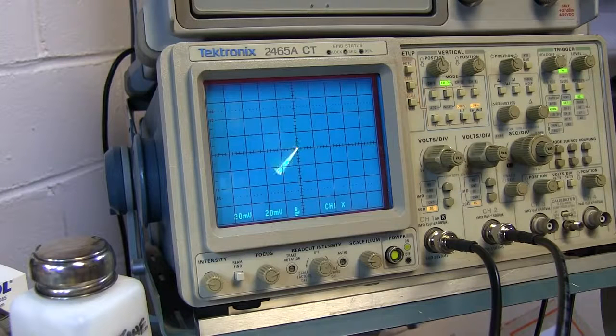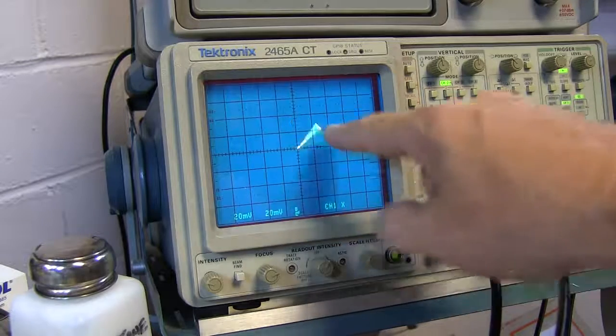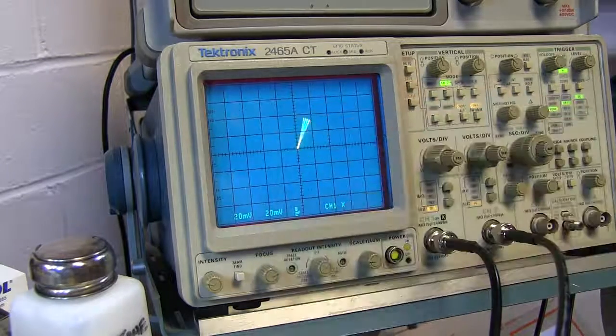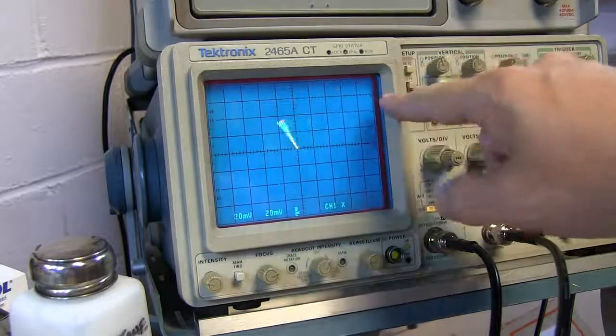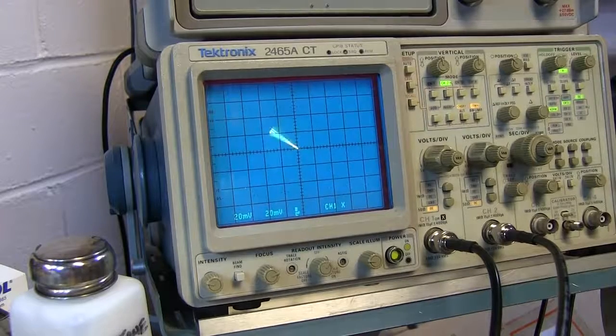If I make that a 2 hertz difference, we'll rotate twice a second, 3 times a second, 4 times a second, and so on. So essentially a frequency offset is represented by spinning that vector around, or essentially a quadrature sinusoid for the I and Q components. So this spinning vector is representing just a constant frequency offset from the LOs.